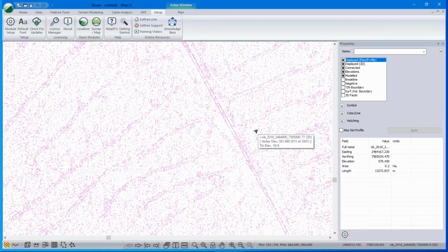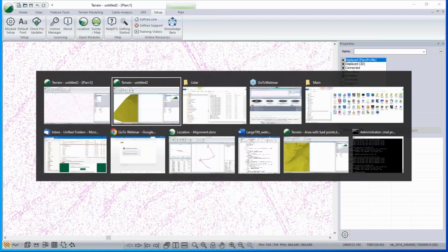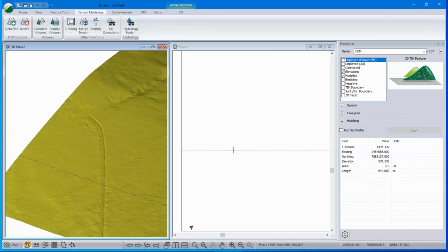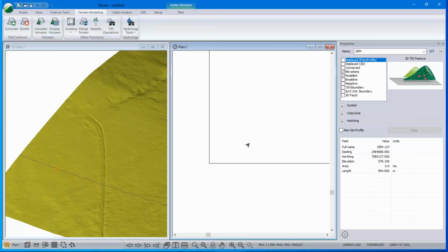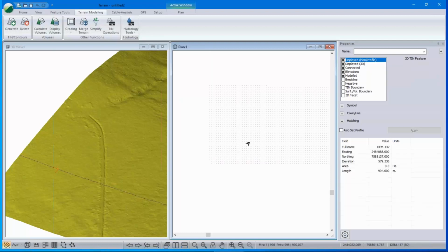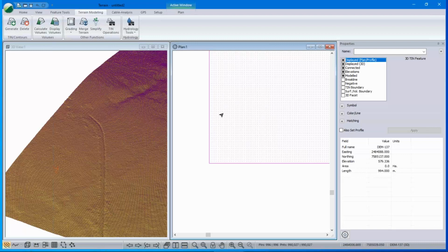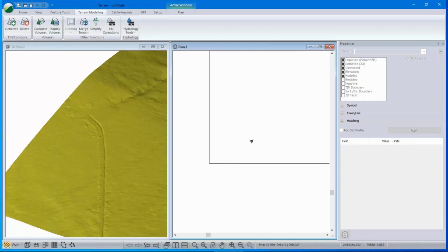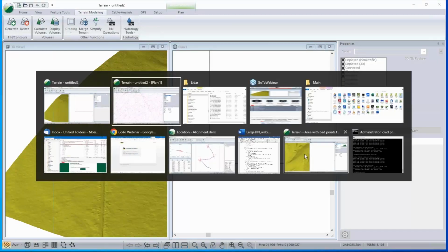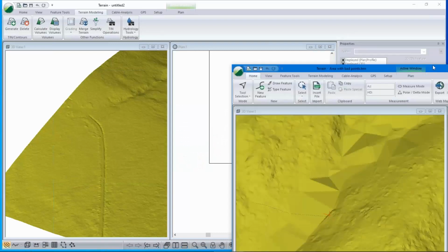It's all here. On the contrary, if I look at that gridded data, I don't know really by looking at the data how accurate it is. It's just a grid that's been interpolated. Now, the interesting thing is that the gridded data originally came from raw LiDAR in general, and that LiDAR was made into a TIN surface. And I've got an example on the screen on my other monitor. Let me just bring it over here.